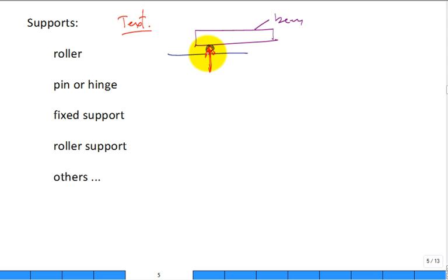But it can't exert a force in the horizontal on our beam. It will freely roll. The roller's not going to prevent it from rolling. That's a frictionless roller. The other thing with the roller, though, is if the tendency of the beam was to try to lift off of the floor, guess what? The roller's not going to constrain it to pull it down. It will only stop it from being pushed into the floor.